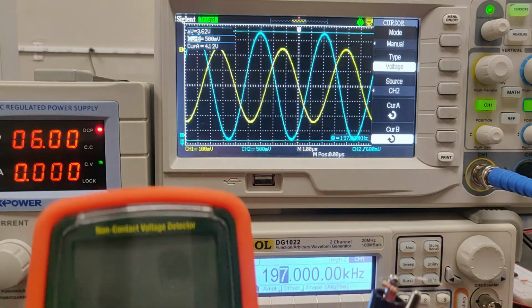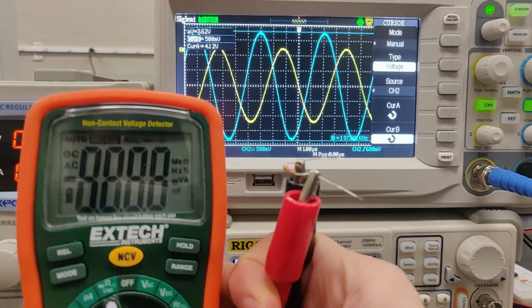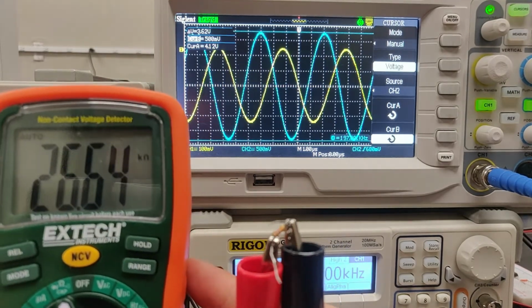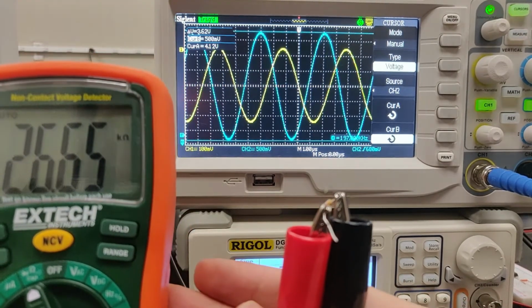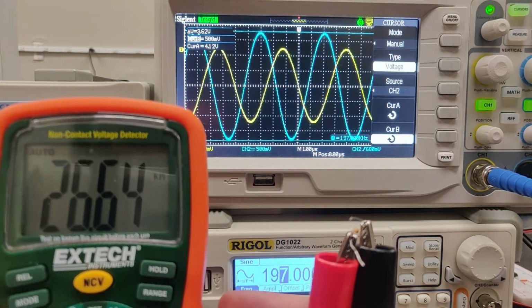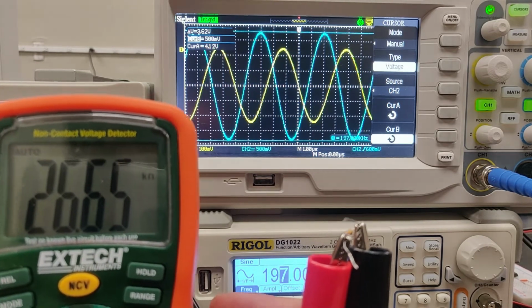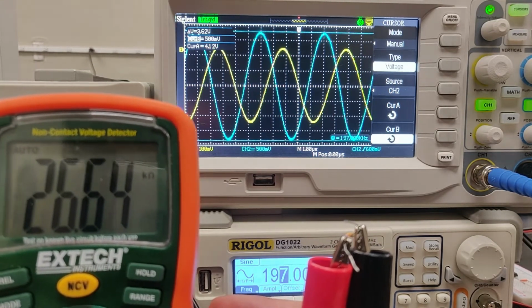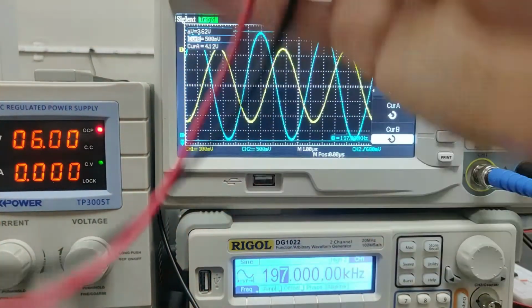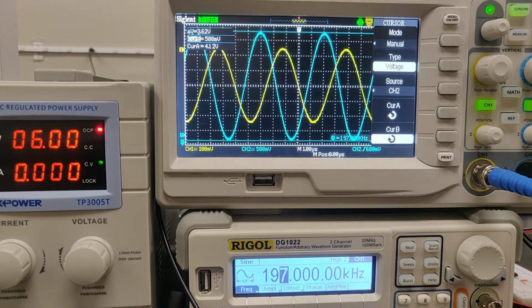So I'm going to be exchanging our 10,000 ohm resistor. The circuit's staying the same, but the 10,000 ohm resistor is being exchanged with this one that's 26.64 or 65 kilo ohms. I'll leave it to you. And so with that substitution, we should be getting something that's relatively close to a gain of 30. Maybe it's a little bit small, but okay.